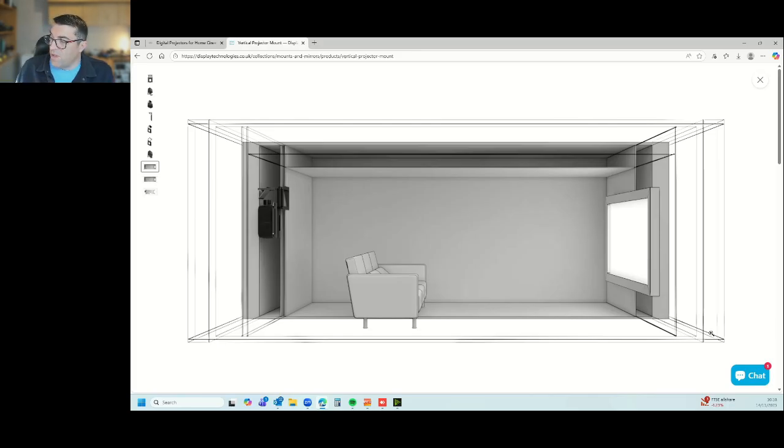Now, one of the things with a micro booth like this is that the volume of air can still be quite large. And typically that projector is not going to be used for 10 hours a day if it's a dedicated cinema. The volume of air can be so large that you don't mind if it warms up to 23, 24 degrees. Who cares? It'll cool down again once the projector stops being used. I have to say these days that's quite rare though, and almost always we are putting forced ventilation into these types of systems.